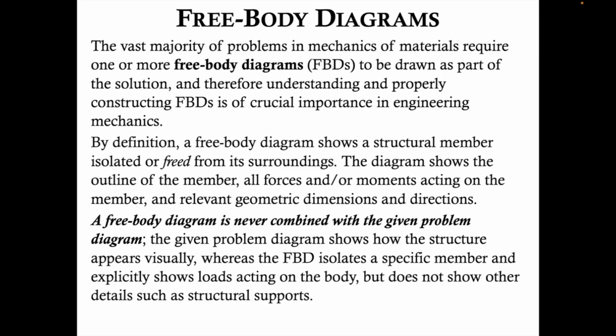The vast majority of problems in mechanics of materials require 1 or more free body diagrams, or FBDs, to be drawn as part of the solution. By definition, as we learned in statics, a free body diagram shows a structural member isolated or freed from its surroundings. The diagram shows the outline of the member, all forces and/or moments acting on the member, and the relevant geometric dimensions and directions, such as directions of vectors.